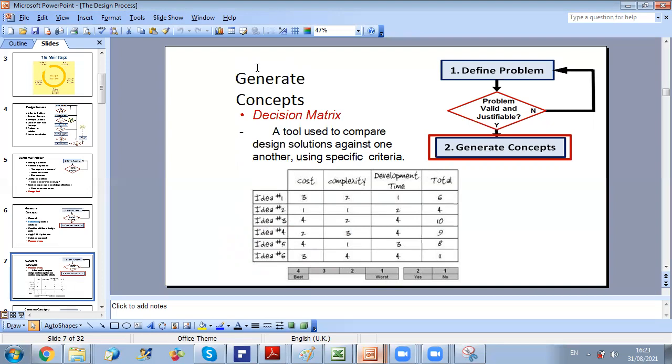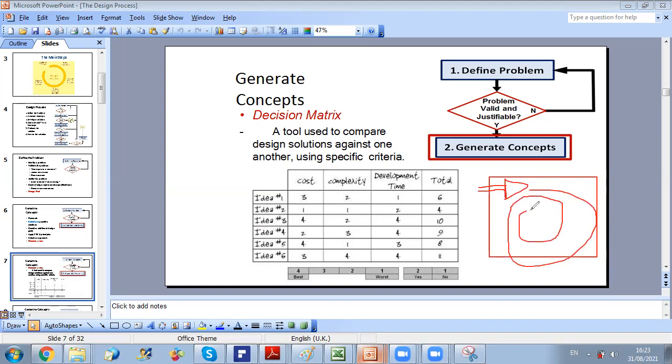And we say that the conventional system used, which is mixed ventilation, is not very appropriate because what is mixed ventilation? If you have a, let's say, a room, in mixed ventilation, you have an inlet and you will circulate your air. So as the name indicates, it's mixing inside the space. So air will be mixed inside the space and then it will be exhausted from the space. In this way, you can remove the thermal loads, but at the same time, this is risky for indoor air quality because it can transport.